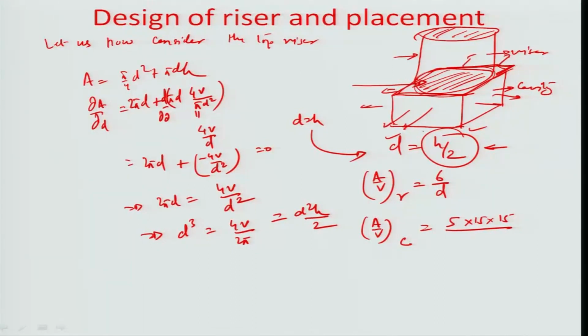although there is going to be some heat transfer depending on if the temperature of the metal is a little different here, but we consider that to be very negligible, because again the temperature of the metal in the riser as well as in the cast before the solidification has happened is more or less in the same temperature zone, unless heat transfer takes place from the other faces, etc. Okay. So, here for example, the area by volume of the casting would become 1/3 centimeter inverse, and we